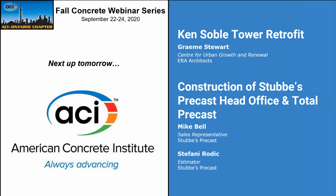It's something that we're very much aware of, and we have had instances where customers have over-vibrated and/or added superplasticizer on site, and they've had to essentially trim off anywhere from a few inches to up to about half a meter's worth of the top of the concrete because they overworked it and the aggregate fell out, and the structural engineer and the engineer of record immediately knew they would not have the required rating on that portion.